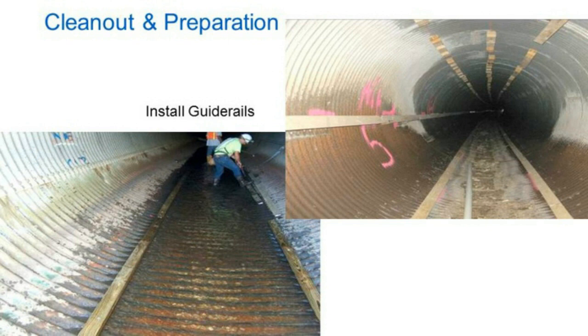When minor bends need to be navigated without the use of elbows, a side rail should be used to prevent the leading edge of the reline pipes from getting hung up on the CMP corrugations while advancing the reline pipe. For smaller pipes where getting inside is not possible, rails can be strapped to the OD of the pipe if space permits between the host and the reline pipe. And in some cases, it's just not possible to put any kind of guidance or blocking in place, due to the size of the pipe and not being able to get into the pipe. So you just have to be a little more careful when you're pushing the pipe through that it doesn't get hung up on the corrugations or any unlevelness if it's a concrete culvert.